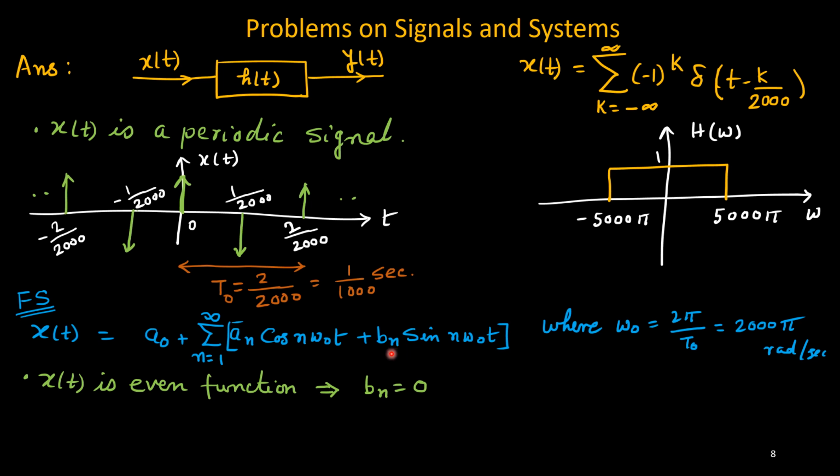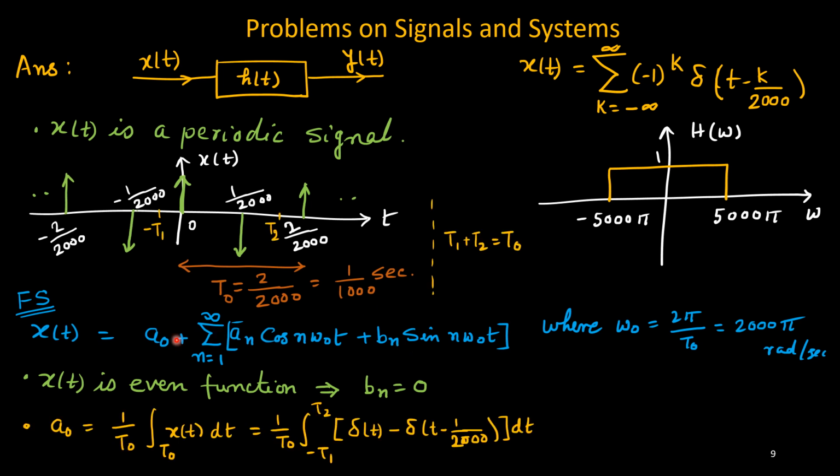That is one property. We can easily show that if a signal is even, then it cannot contain any sine function, because sine is an odd function. So an even function can be expressed by a summation of even functions. a0 is DC, which is even, and an cos n omega t terms are all even functions. But sine is an odd function, thus the bn terms should be 0 for all n. So no need to consider any bn, right? Now the signal can have a0 and an.